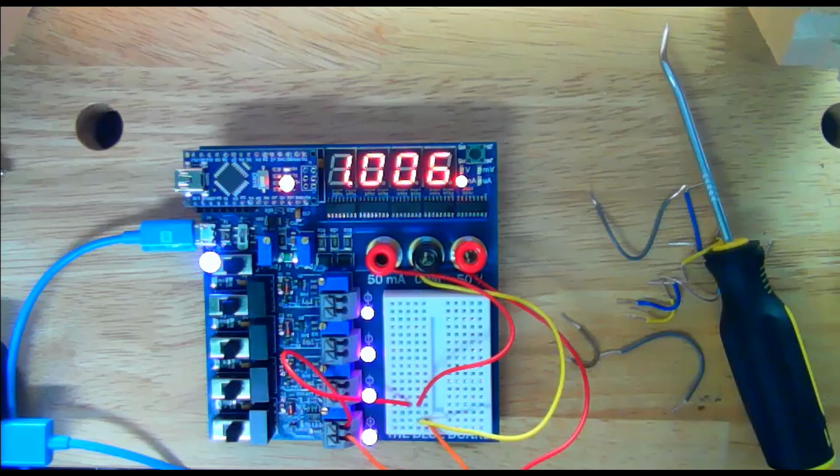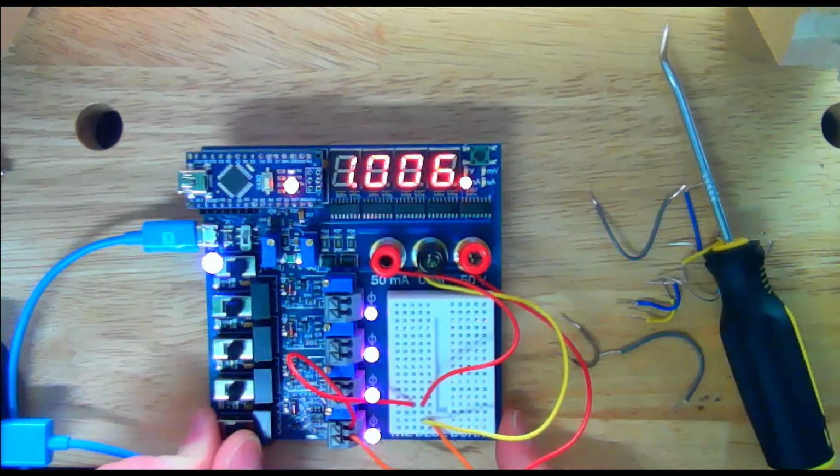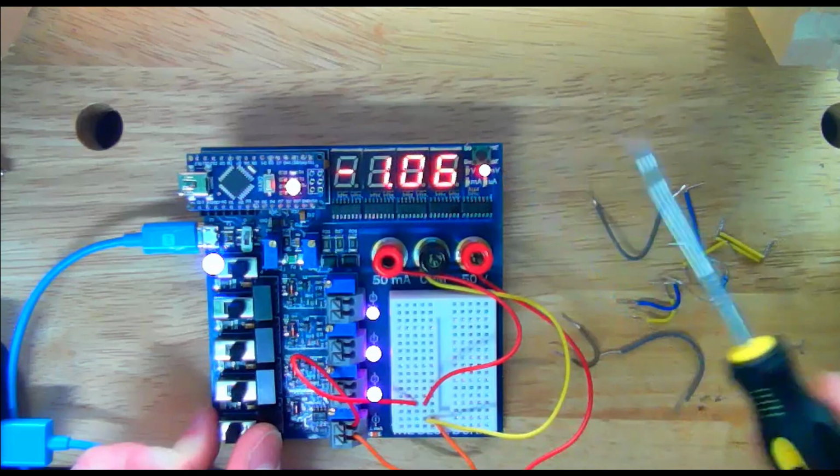We're just measuring it using the board. And I think I pretty much went over the basics. We'll talk more about features of this board as we do different labs, but for right now, this is what we got. Now let's just try for fun de-energizing the current supply. And that current drops down to the microamps, 97 microamps, 60 microamps, 39. As soon as that current gets too low, the board's going to detect that there's no current, and it's going to switch back to measuring voltage.